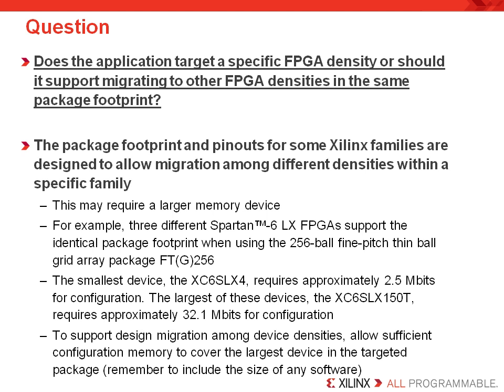Another common question is, does the application target a specific FPGA density, or should it support migrating to other FPGA densities in the same package footprint? Some customers are unaware that the package footprints and pinouts of some Xilinx device families are designed to allow migration between different densities within a specific device family. This is important because if the user is planning on purchasing a memory device in advance, you may need to consider selecting a memory device that has sufficient size to target the largest of those chosen FPGA family densities.